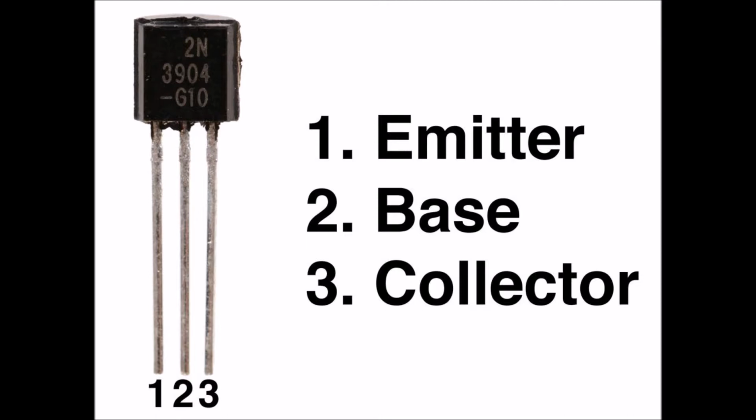One that describes the collector current versus the emitter current when we place the base at electrical ground, symbolized HFB, and the other that describes the collector current versus the base current when we place the emitter at electrical ground, symbolized thus. The quantity HFB equals the ratio of the collector current to the emitter current at a given instant in time with the base grounded.